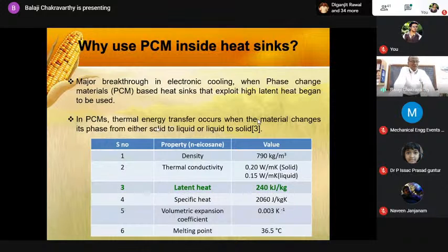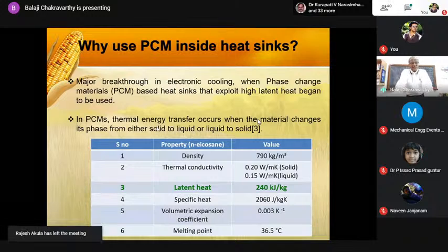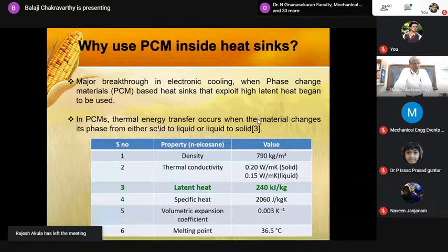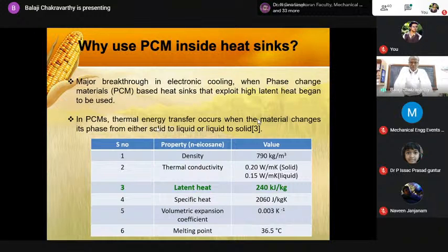Of course, there are some fundas there. The melting won't happen at one temperature; there is a solidus temperature and a liquidus temperature. There is a mushy zone. So if you have to model it using COMSOL, Fluent and all that, there is something called the enthalpy porosity formulation, so you have to be careful. If you want to get into numerical methods, it takes many years of hard preparatory work to do research on this.